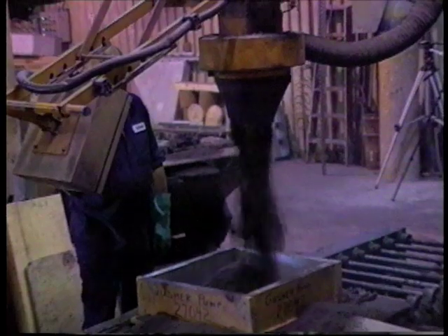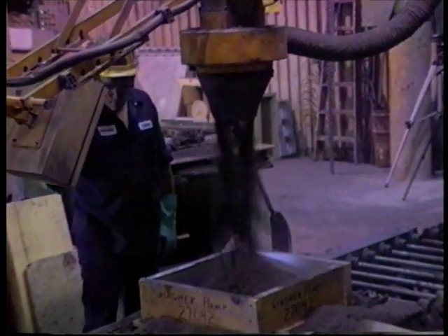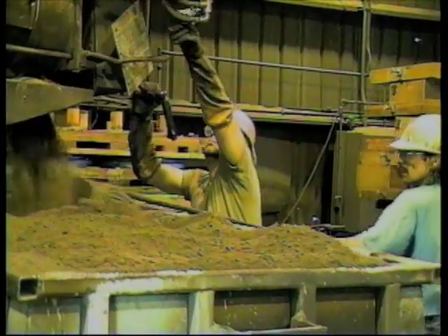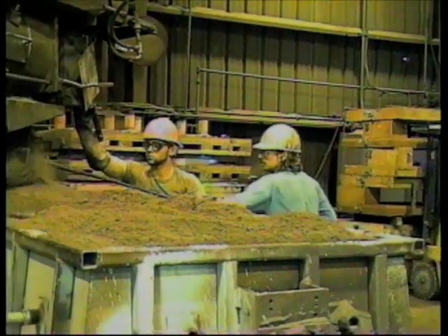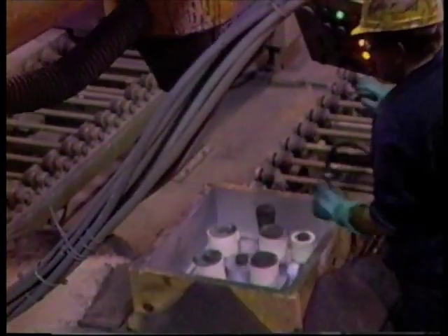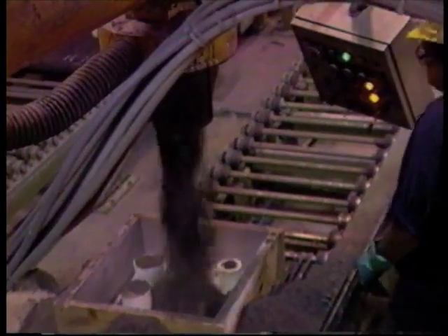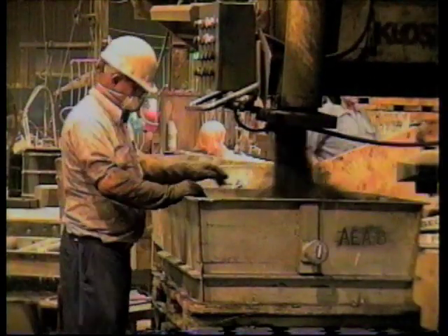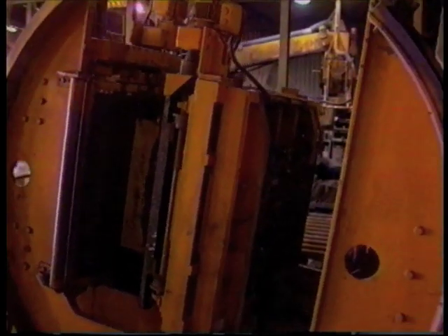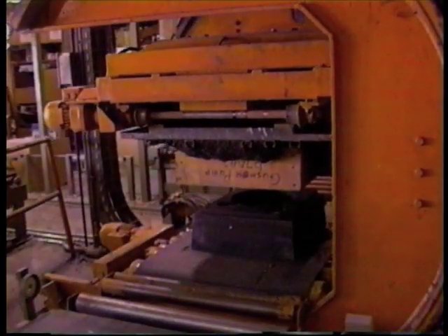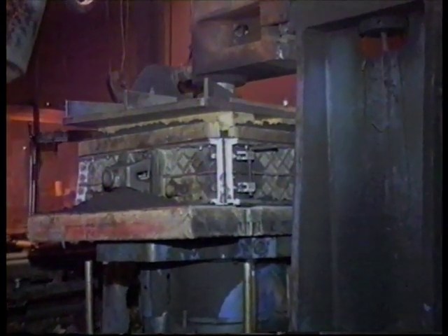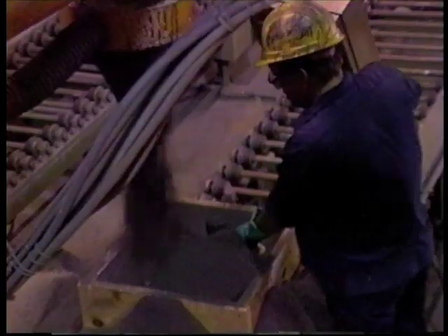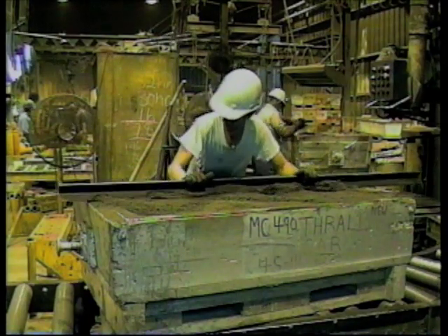Sand may be recycled. The most popular sand mixture used to make molds is green sand. Green sand is sand bonded with clay and water. Other binders can be used to make molds. Chemicals that bond sand together are called no-bake binders. The properties of bonded sand make it possible to use all types of mold-making equipment, from hand molding to high-production molding machines. Generally, sand is placed around the pattern, and in the case of clay-bonded sand, rammed to the desired hardness. In the case of chemical binders, the mold is chemically hardened after light manual or machine compaction.